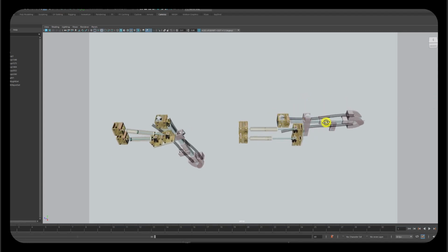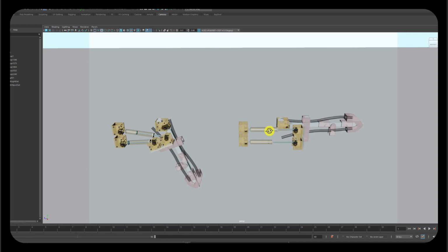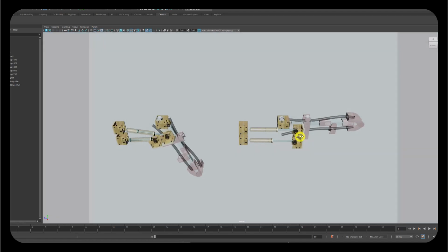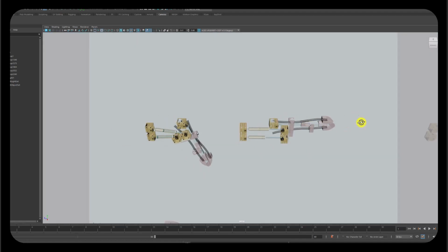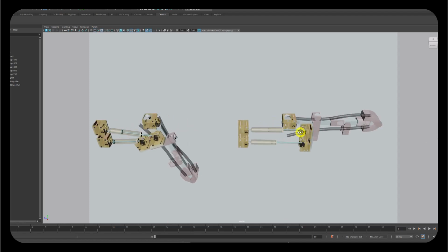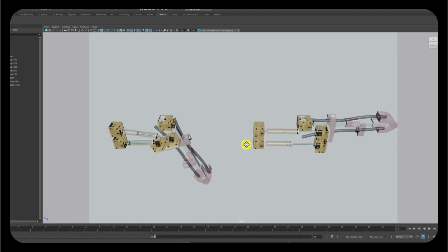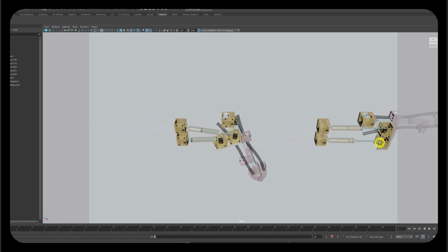This is one finger in the sort of neutral position where these two hydraulic cylinders are at that condition. And if this hydraulic cylinder holds still and this hydraulic cylinder retracts its piston rod and piston head, then this whole entire finger will rotate around this joint and it flexes the finger.